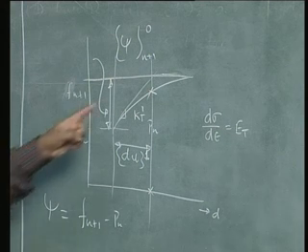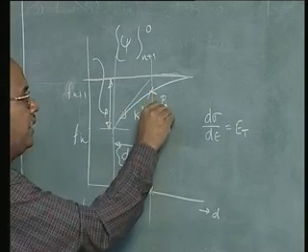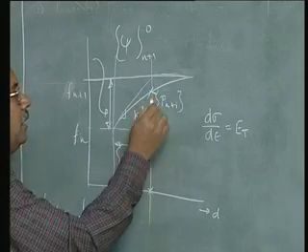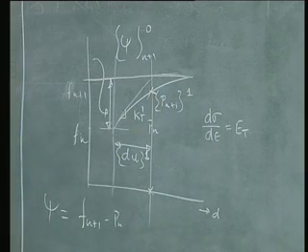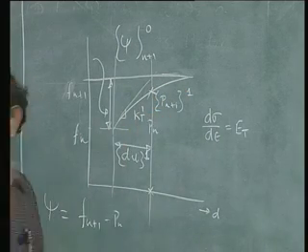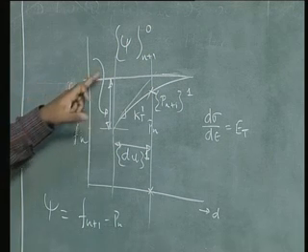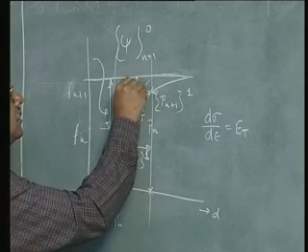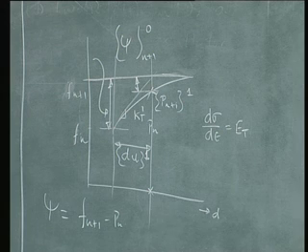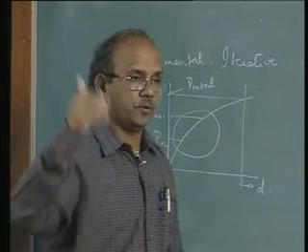I have only calculated the internal force which is given by that point, which let me call as Pn plus 1 at the end of first iteration, or Pn plus 1 if you want to write it outside also, right. Now what is the error now? Error is between Fn plus 1 and Pn plus 1, that difference. So now the error has reduced to this. That is my error at the end of my first iteration, which I am going to use for second iteration as the input, right.